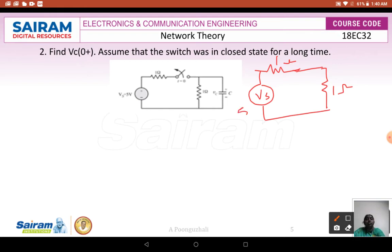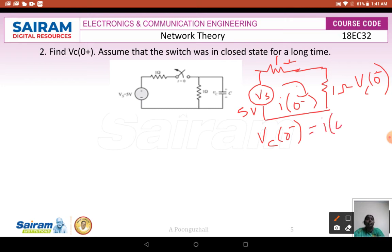This is going to be your 5 volts. When the switch is closed for a long time, the initial condition is at 0 minus, so I want to find out what Vc of 0 minus is. To find this Vc of 0 minus, I have to find the drop across this 1 ohm resistance. So Vc of 0 minus is I of 0 minus into 1 ohms. I of 0 minus is the total voltage, 5, divided by the total resistance, 1 plus 1, so into 1, that is 2.5 volts.